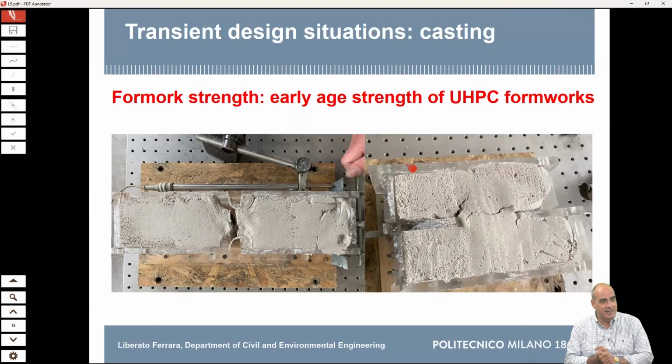And I always like to put some research content into these slides. Actually, this is a work which has been done by an IIT Madras alumnus who has been doing his PhD with me in Milano, and in 1 month from now is defending, so it's closing up. Some of you know him, Sriram Kompella. We did tensile and shear tests on fresh concrete. That was for 3D printing, because we wanted to understand how fast we can go with printing before the filament breaks, or how fast we can pile up the things.